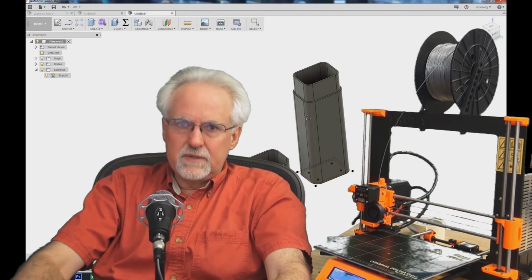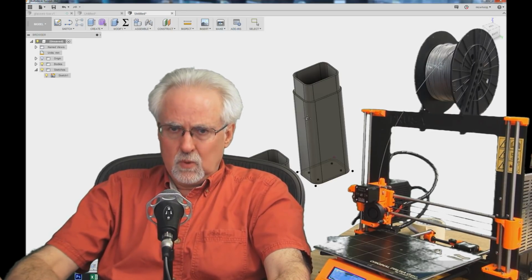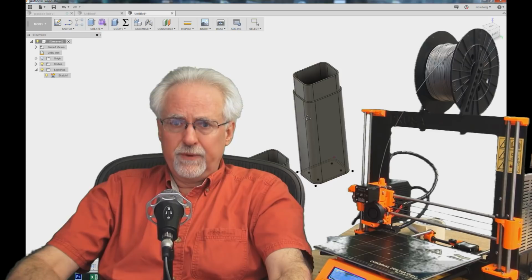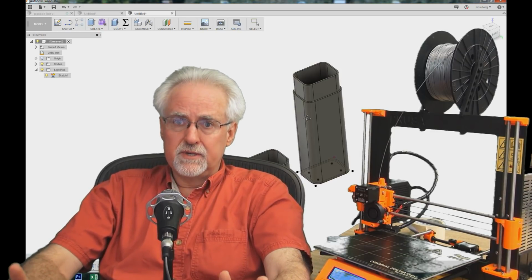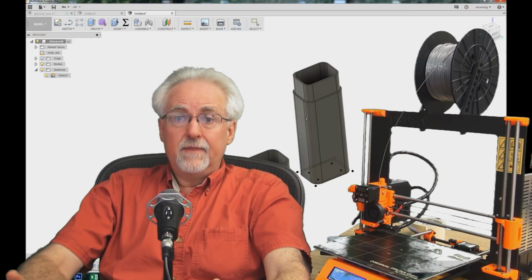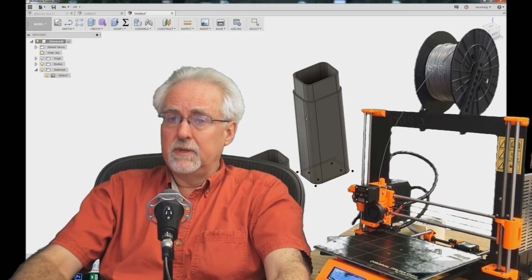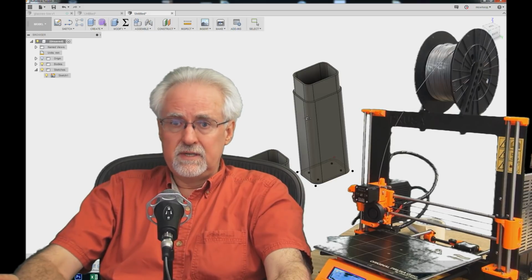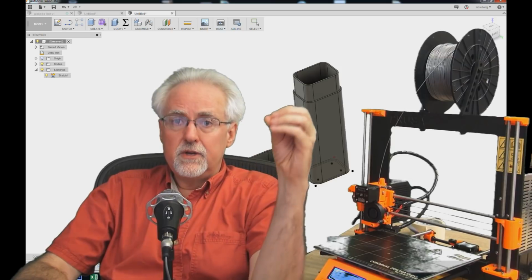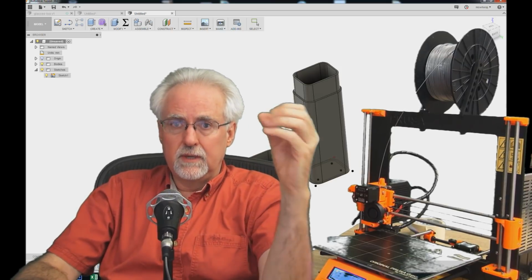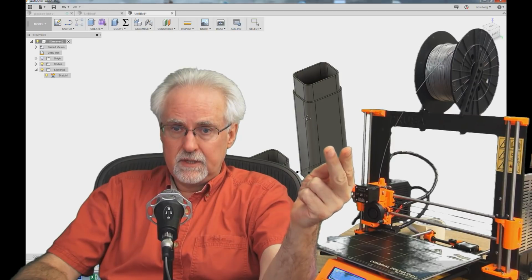Man, I hope this has been helpful for you guys. It's really, really important. Let's think about what we've learned. You win or lose the battle in the two-dimensional sketch plane. Did you see once we defined things properly in the two-dimensional sketch plane, everything else was fun and easy and worked great? In the two-dimensional sketch plane, you are mindful and deliberate about dimensions and about position.